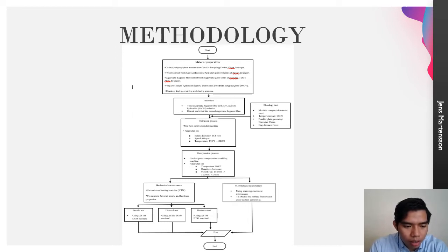Then the product of the extrusion process will be transferred to the compression molding machine for the compression process at temperature 200 degrees Celsius, duration 5 minutes, and mold size 150 mm times 150 mm times 3 mm. Then the specimen will undergo the mechanical measurement, that is tensile test, flexural test, and hardness test. And for physical measurement, a scanning electron microscope will be used. All the data will be collected for data analysis and the process ends.